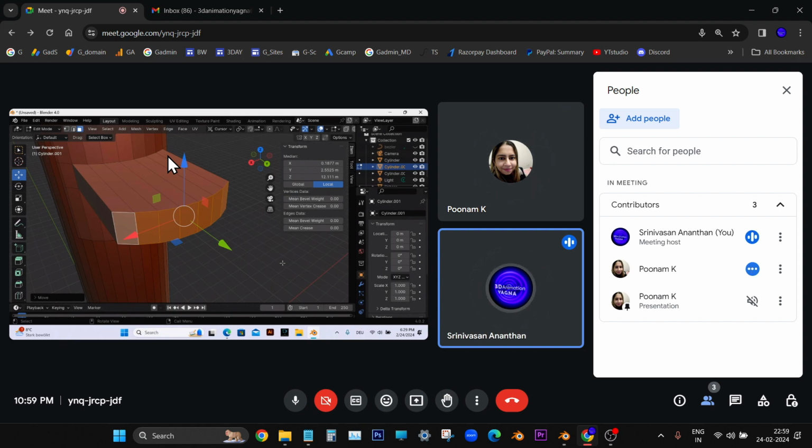Now don't change the view. Press Alt E and extrude faces. Little move forward. Drag the mouse forward. Just enough. Stop the function. Now, do you see one more line there on the bin? So this is why from there it has extruded. From there it has been duplicated. So that is the difference between movement and extrusion. Right. Now you can undo it.